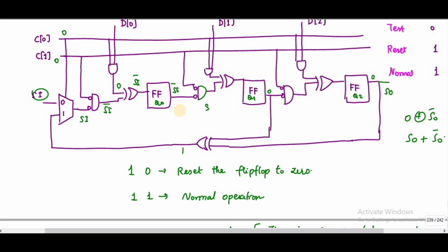If the D input is held low, the Q output loops through the pseudo random bit sequence, which can serve as an input to the combinational logic. So if the D inputs are taken from the combinational logic, they are combined with the existing state to produce a syndrome. Okay. So if the D value is not taken, it will act as a PRPG, PRSG, or if I am taking the values from D input, it will act as a signature analysis.